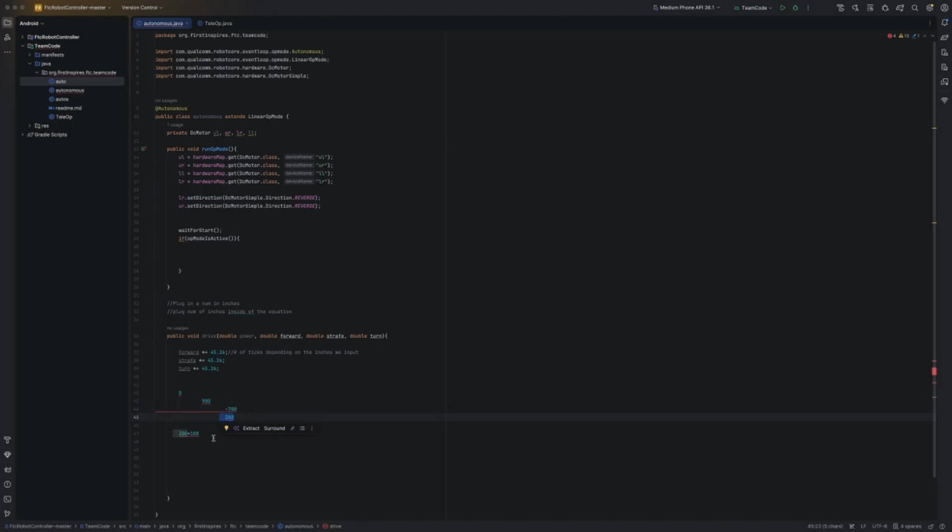We basically have to reset our encoders and our motors to prevent that problem from happening, and not add up or stay at one position. Let's say the encoders were already converting to inches. It was already at 3 inches, and I wanted to move another 3 inches.